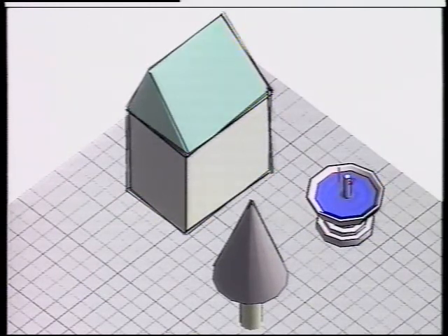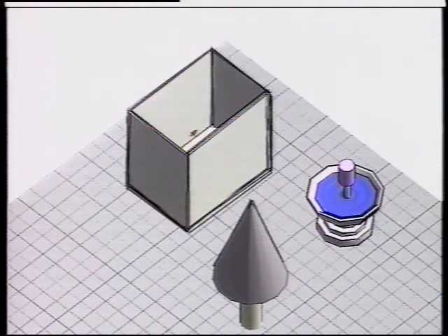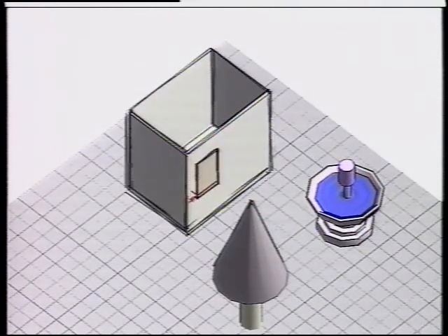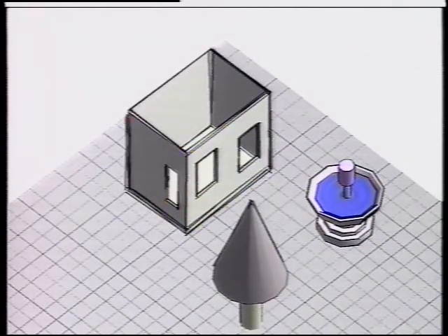CSG subtraction is inferred automatically based on the direction that lines are drawn. To hollow out the house, notice that the vertical axis of the new cube is drawn down into the base of the house. By quickly clicking on the new cube, we can gesturally delete it and see the effect of the CSG operation. The CSG subtraction technique is used again to hollow out 2 windows and a door. Again, the CSG operation is inferred whenever the user draws a new object through an existing one. The direction of the gestured lines is very important.